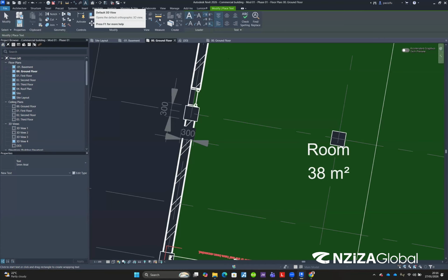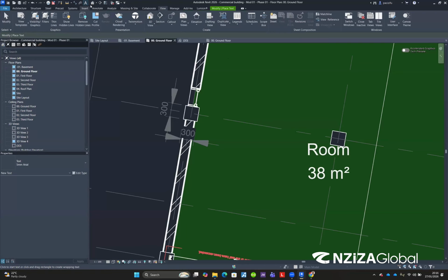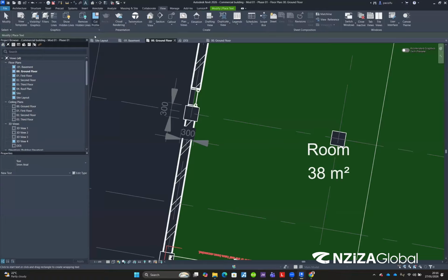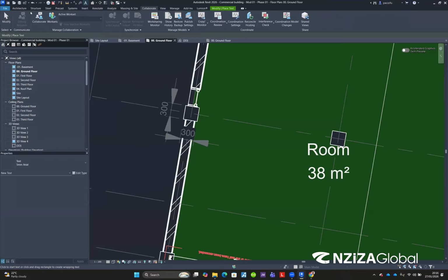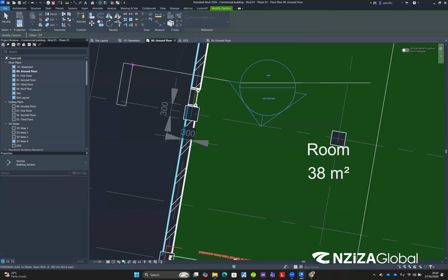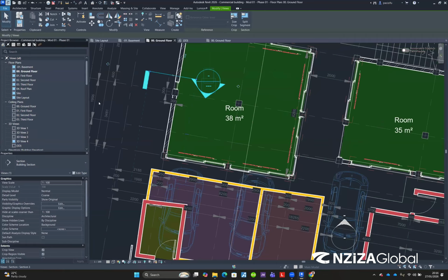We don't need to go in view, then go to 3D. You just come here and click on 3D. We have these sections. Maybe you are working with Revit and someone needs some details in your drawing. You will not come in files, component, view, go to section. You just come here and click on section. Then you start drawing your section here. Then it will provide a section.